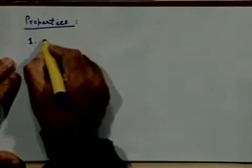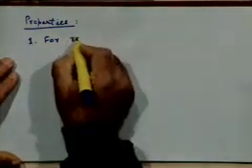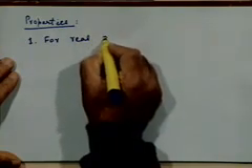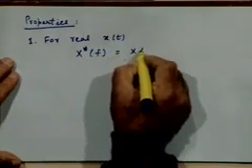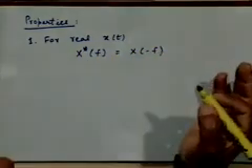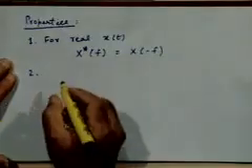Now a quick review of the most important properties of the Fourier transform. Some of the properties are the same that we already discussed in the context of Fourier series. So for a real signal x of t, x conjugate f would be equal to x of minus f, which is again equivalent to saying that the magnitude spectrum is even symmetric and the phase spectrum is an odd symmetric function of the frequency for real valued signals x of t. Right? So need not spend too much more time on that.